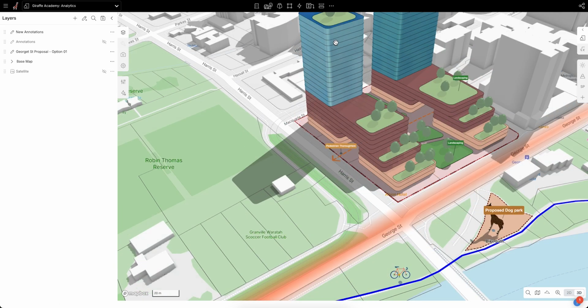So now let's take a look at the measure tool. I want to navigate up to the drawing toolbar, click on measure, and we've got two types of measurements here. So we've got temporary dimensions and areas. If I grab the tape measure there, run it across this length of the site, double click to finish, it will actually disappear. So it's a quick way of finding out that dimension. And also the shortcut is M on your keyboard. So that's a nice little handy one when you're looking to quickly get a dimension from your project.